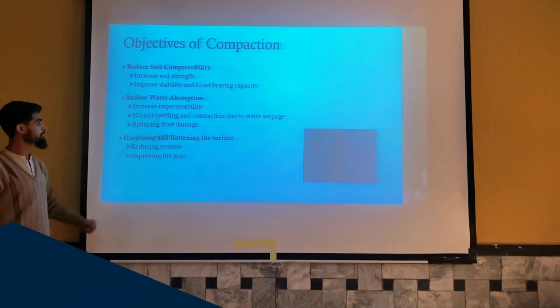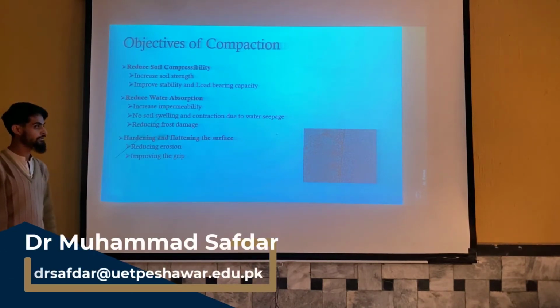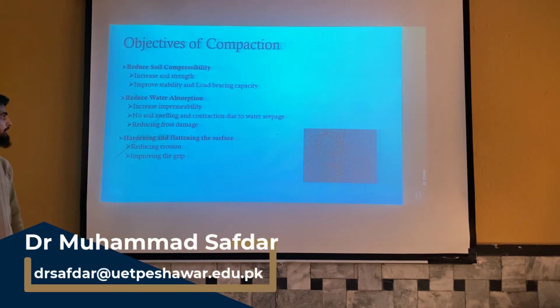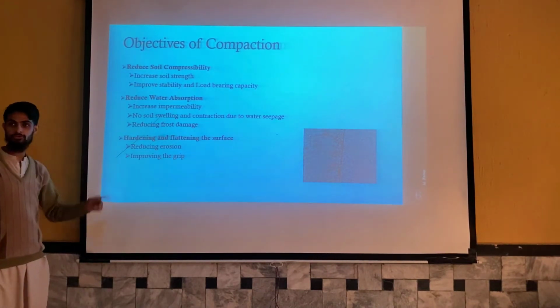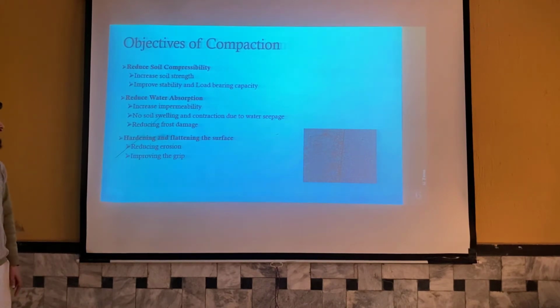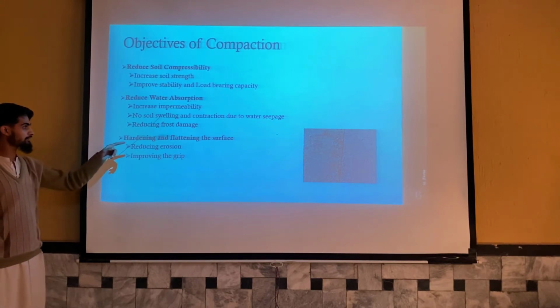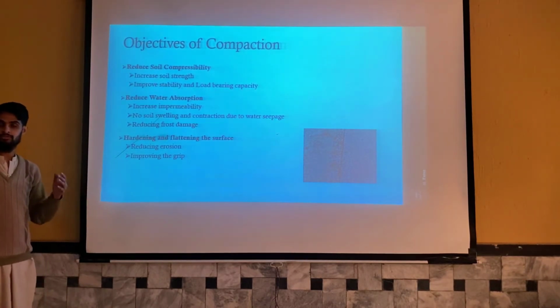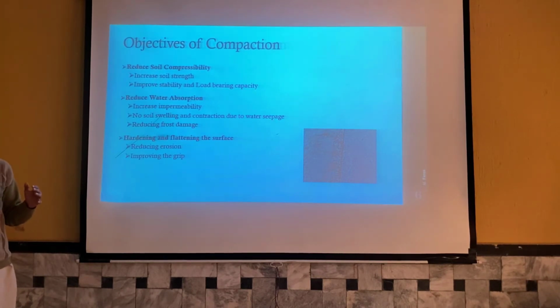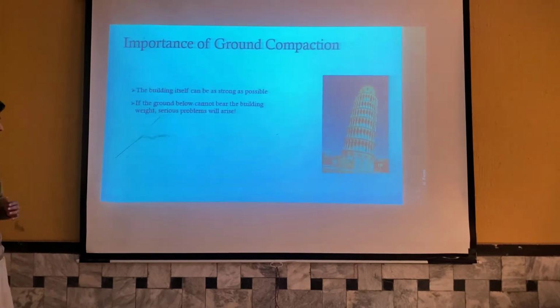Similarly, there is no soil swelling and contraction due to water seepage. When the impermeability is increased, water cannot seep into the soil. Similarly, the actions of frost, the cold and the hot actions, are reduced when we do proper compaction of the soil. Similarly, hardening and flattening of the soil reduces the chances of erosion and improves the grip of the soil. As a result, the buildings and other structures can sustain for a long time.